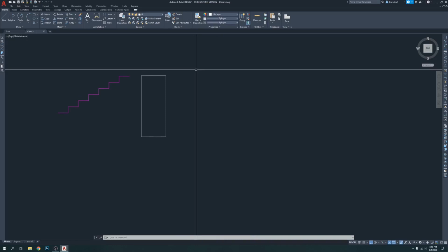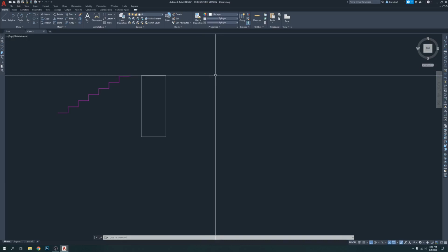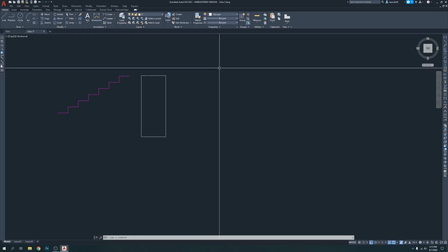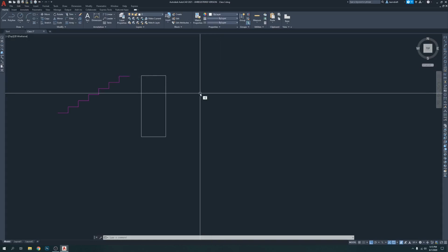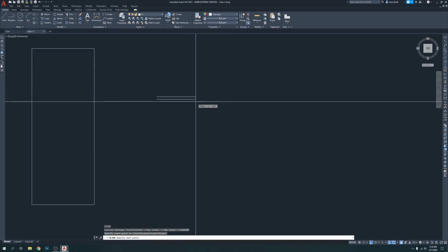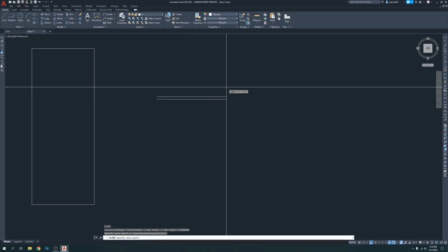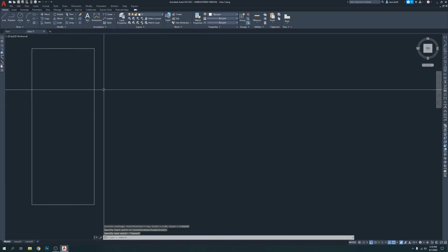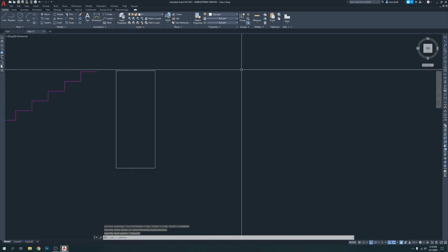Now multiline is, I think I never used. I worked a lot, but most of the time I did not use multiline, but there is a tool multiline I want to share with you, which command is ML, enter, click. You see automatically, by default 2 lines are selected. So let's say you are drawing a frame, the same way we drew this box.